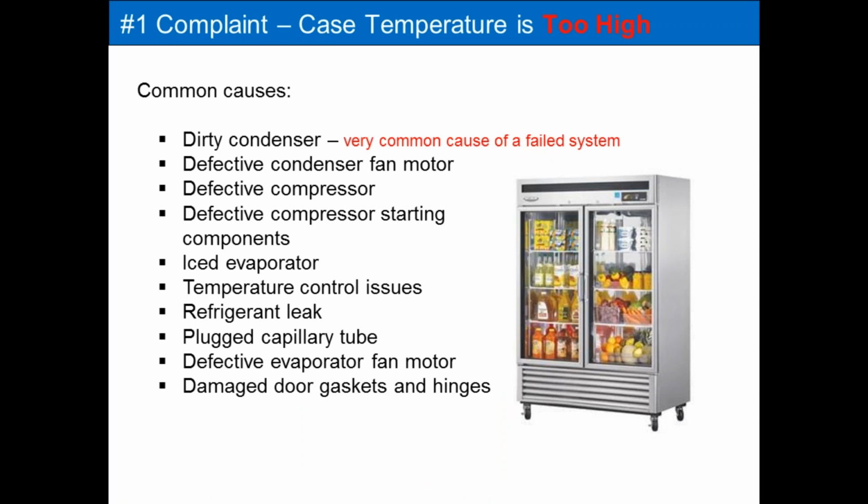And the number one reason for you being out there is going to be the case temperature is too high, right? You're going to get a call from a customer saying, hey, my case is too high, the health department was just in here and it's supposed to read less than 41, let's say, and it's reading 45, or it's at 50 or 60 degrees. That's a pretty common call. But the reasons for a case temperature that is higher than normal can be very diverse. What I've listed on the screen here are some of the most common reasons why your case temperature could be higher than normal.